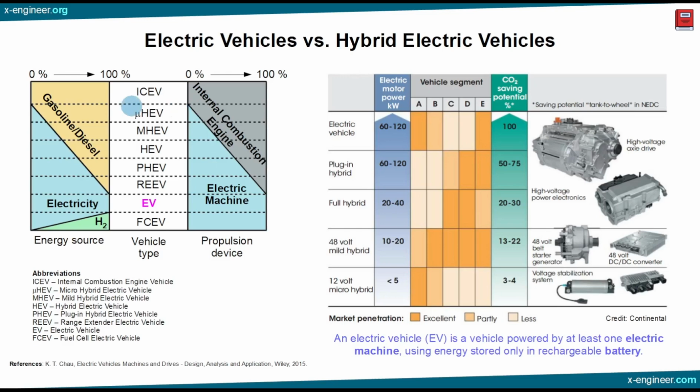In the case of micro hybrids, that low voltage system is smart and has an alternator that can go in standby mode. And while the alternator is in standby mode, the low voltage battery will sustain the low voltage system.